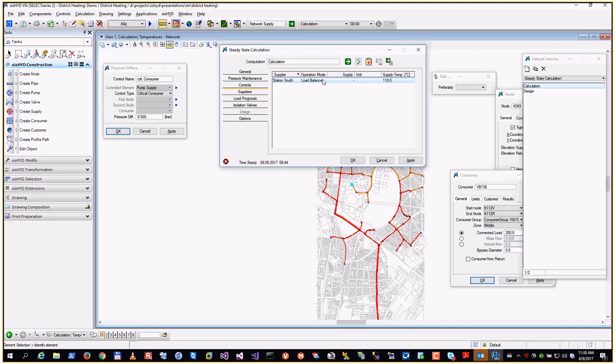So we can write this equation here, that the mass flow equals the heat load divided by the heat capacity times delta T. So this is the 60, this is the 140. The heat capacity, we can compute an average one from a thermodynamic library. So this way we get an estimation for the mass flow.